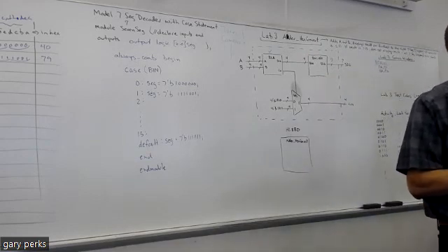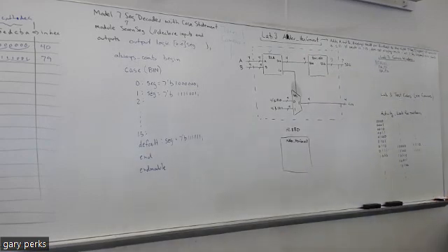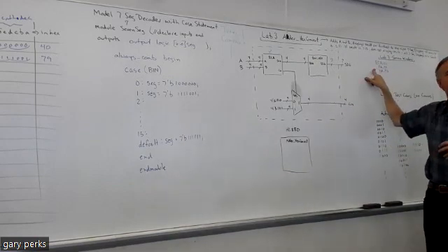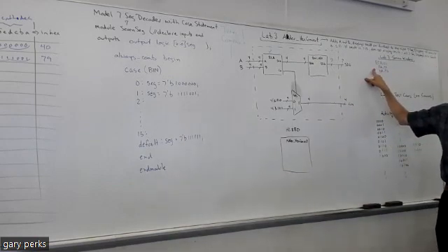Should all of the names work, or maybe I have to rename stuff? You don't have to rename. I would just leave it all the same and use the same name. The thing with Vivado is that if you start renaming stuff afterwards, it can somehow screw it up where it can't find it any longer.